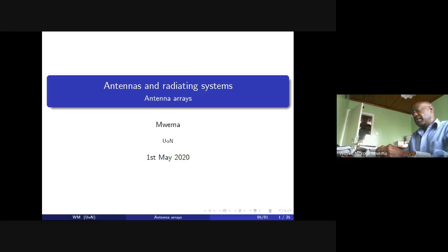So the same thing is that we can always use the knowledge obtained from treatment of elemental antennas, that is the Hertzian dipole and the magnetic loop, to analyze antennas for which the length of the antenna is much larger than or of the same order of magnitude as the wavelength of the signal, and we use superposition of the small contributions of the little elements of current that we have divided that length into.